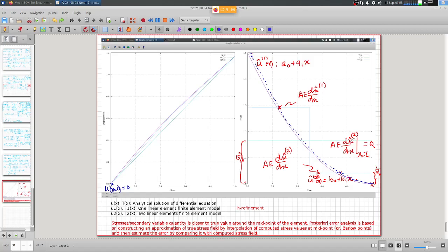The boundary conditions are accounted for during the process of assembly of individual element contributions of weighted residual, domain residual statements. The boundary terms associated with domain residual statements, the natural boundary conditions and essential boundary conditions would be imposed on those. That is what we did here.